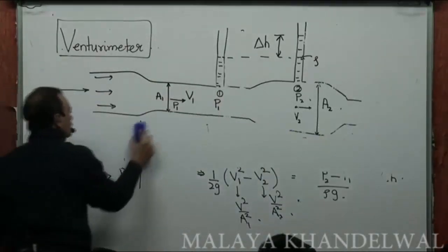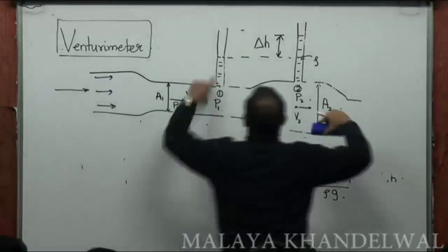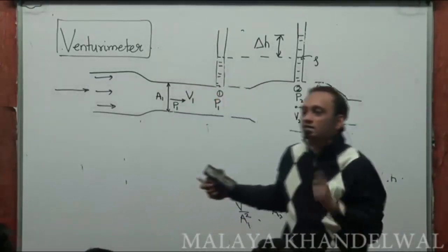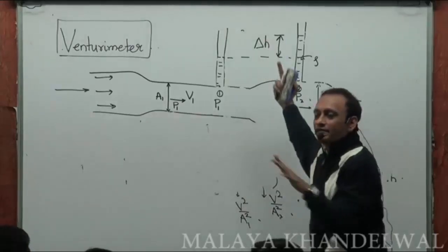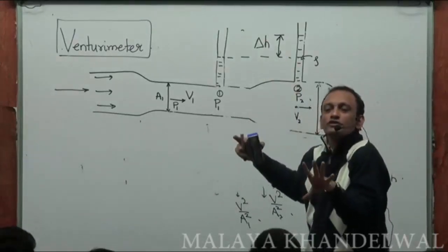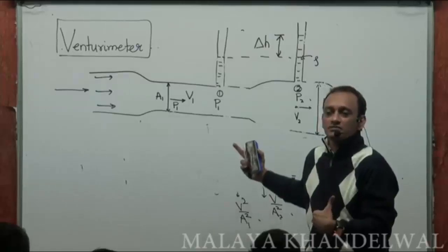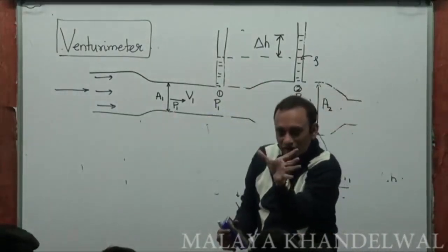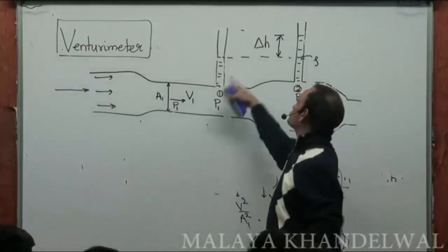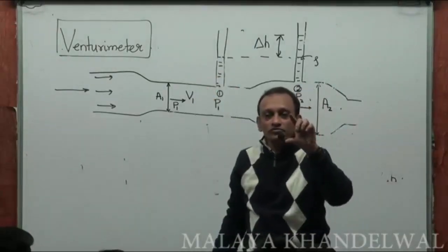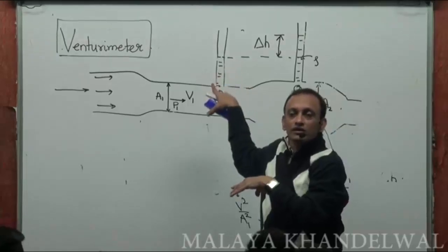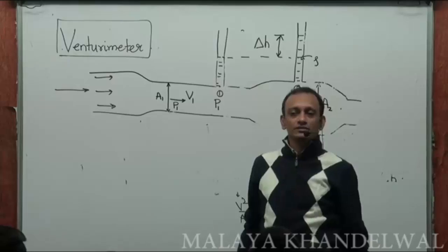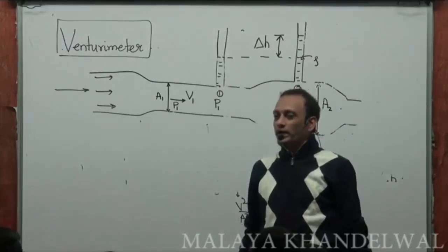And again, even if it didn't, this volume is not like gallons of liquid. It's a small amount sampled there, and therefore there is no major loss of accuracy in making this assumption. I've drawn it this big. The actual arrangement could be really small, and these could be narrow channels, and the volume of the fluid that rises into these limbs is really, really small, my friend. So it doesn't affect the total working significantly.